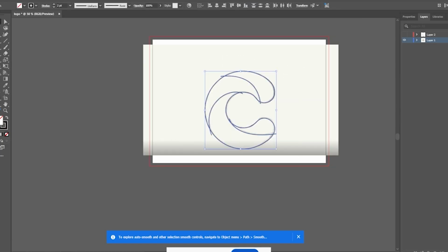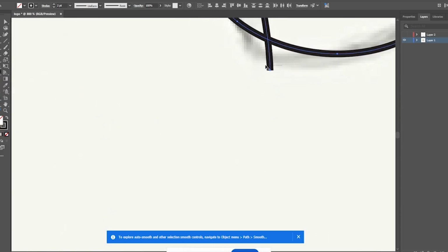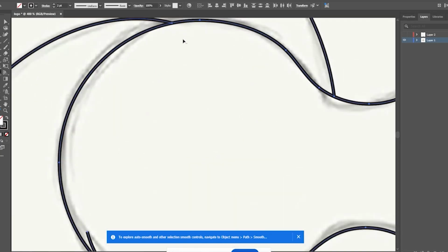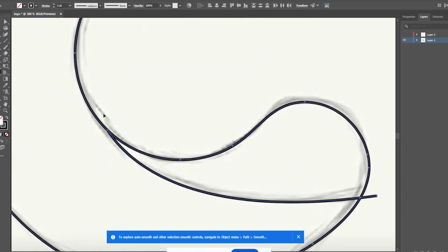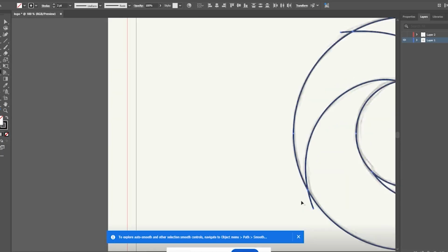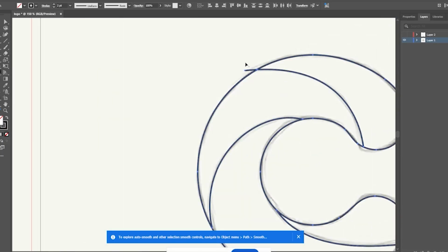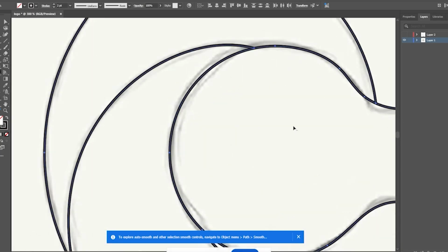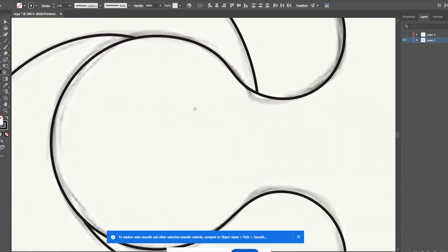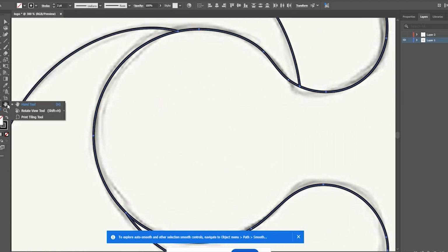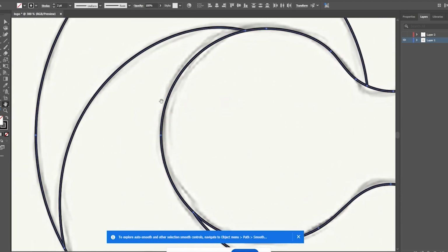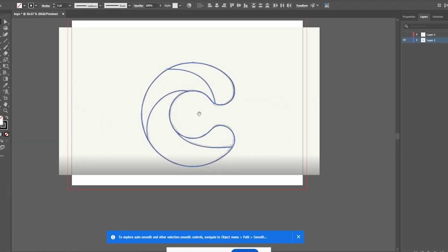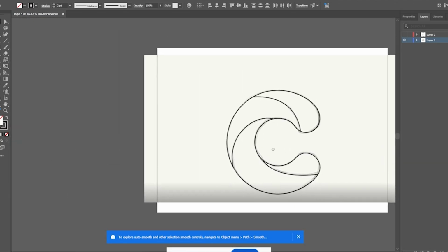Now select everything together. I will use the shape builder tool quickly. I am zooming in and holding down the Alt key to delete these extra sections. It deletes. As we mentioned, holding down the Alt key allows you to delete the extra parts. Alright everyone, when I perform a zoom in, if you keep the spacebar on your keyboard held down, you can move this. This becomes your tool, it becomes the hand. If you continue to hold down the spacebar on your keyboard, you are able to move and navigate it.